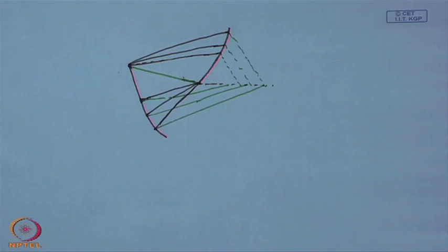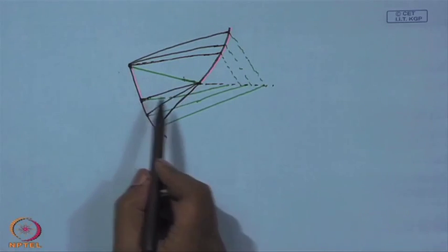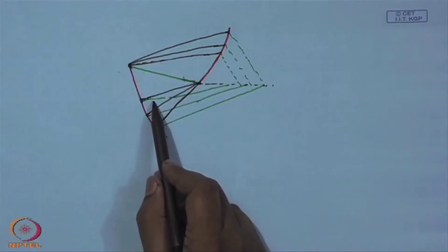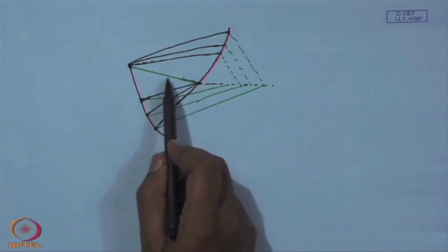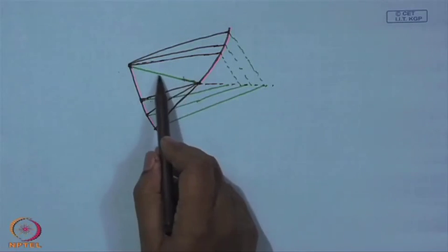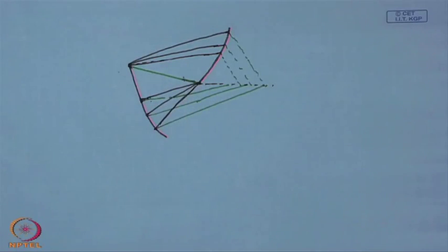So, you see that in the far field, and particularly the flow downstream, is quite complex, with shock expansion interaction and then reflection, and again interaction of those reflected waves and so on. However, in these cases these reflections will not be incident on the flat plate itself, and consequently the flow over the flat plate, or in the immediate vicinity of the flat plate, will remain undisturbed by these shock expansion interactions.